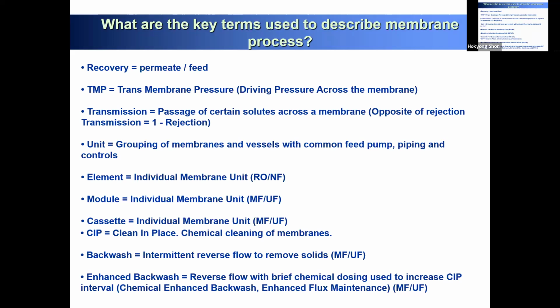So when you have this ultrafiltration membrane, you continuously pressurize, and then your organics or particles continuously accumulate on the surface. So sometimes you have to backwash, and then they detach, and you can easily remove the foulant.